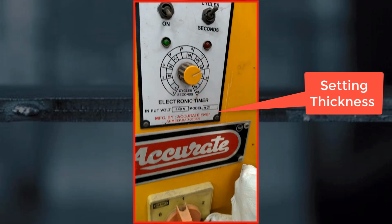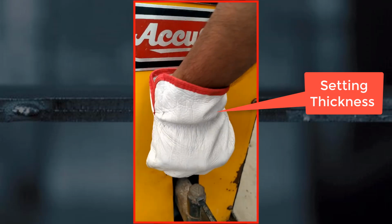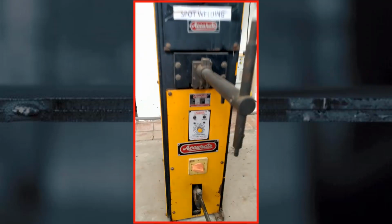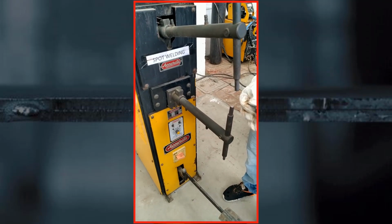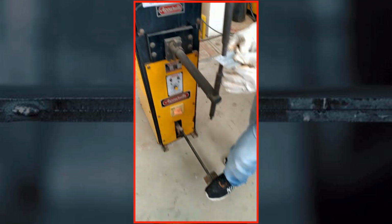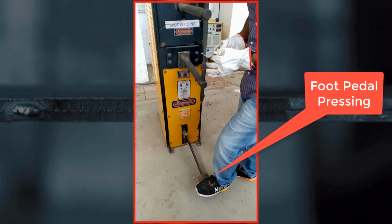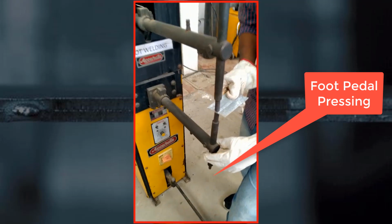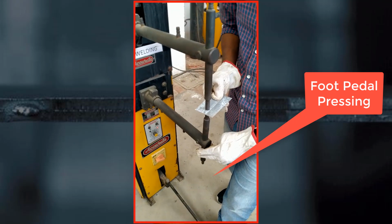Here we are setting our cycles at around 40 to 45, then we can set our thickness, right? It means the plate thickness is used for this setting. For example, here we are using a galvanized iron sheet of 1 mm thickness, so according to that we can set our thickness.